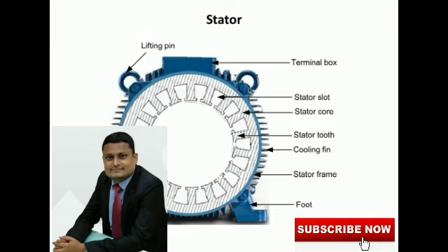So these conductors need to be distributed among the slots. Next, the number of stator slots Ss. The guideline is that the slot pitch should be between 15 to 25 mm.